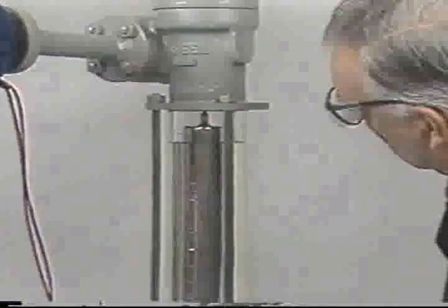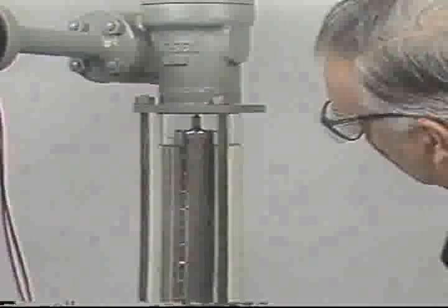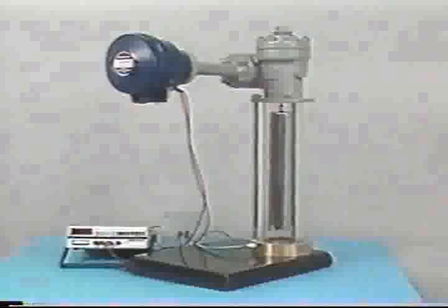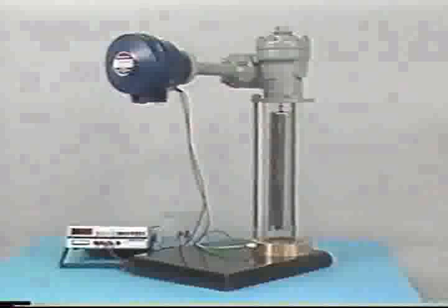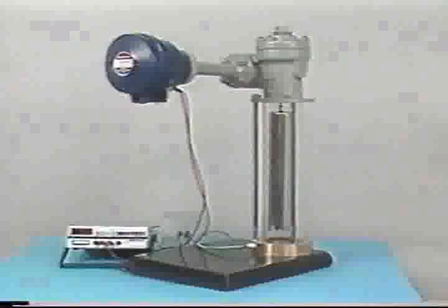Actual liquid level is the input you'll use for calibrating a displacement level transmitter. For this level instrument, the process conditions are not simulated but are replicated for calibration. The most appropriate liquid for replicating process conditions is a safe liquid with the same specific gravity as the process fluid. And the calibration setup includes a milliammeter as the output standard and a 24-volt DC power supply. The output is connected in a series circuit.